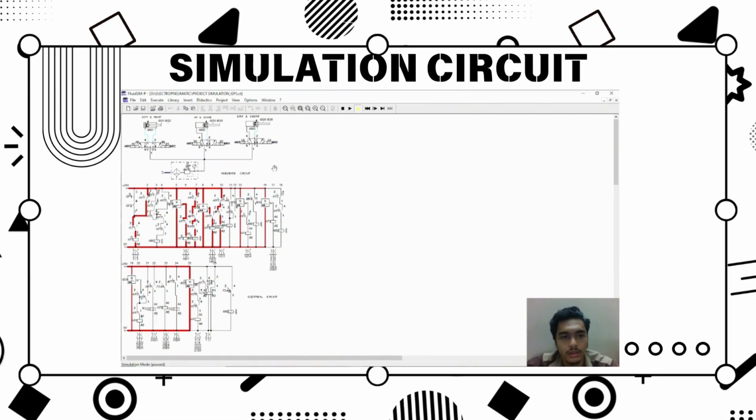The piston rod -MM3 will fully extend position for double acting cylinder DSC. After piston rod -MM3 fully extends, magneto proximity sensor -BG6 will activate and energize the relay -KF3, that through relay contact -KF5, and relay contact -KF3 will open and turn off the current for solenoid coil -MB3, which is here, and relay contact -KF3 will close and flow current through -KF7 and activate timer -T1 for 3 seconds.